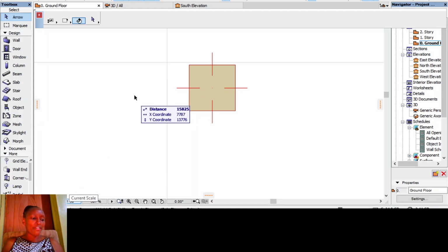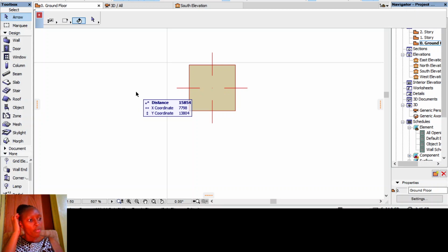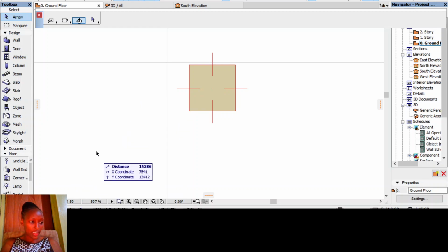The name of the command varies depending on which window is active. So select either a standard scale from the pop-up list or type a non-standard scale into the numeric input field. So you can select a standard scale, or you can just input the scale that you want. The name of the given window is displayed in the caption of the dialog box. Standard scales are shown according to either metric or imperial standards, depending on the length unit settings.